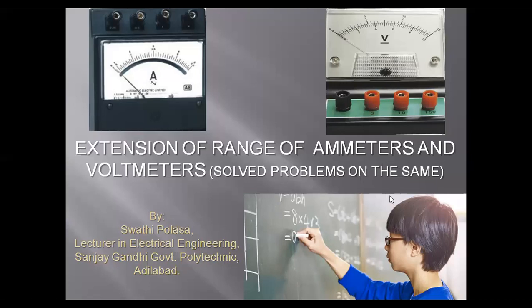You can see in my first PPT, we have an ammeter here, and there are different terminals here. Similarly, we have a voltmeter with different terminals instead of two. And here it is clearly visible that it states 3, here it states 10, here 15. You can see different ranges on the scale. It's from 0 to 10, 0 to 3, and 0 to 15.